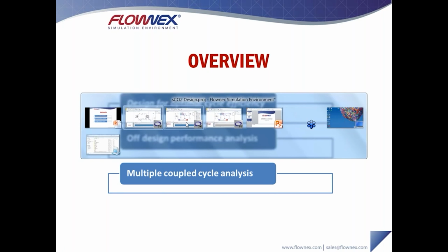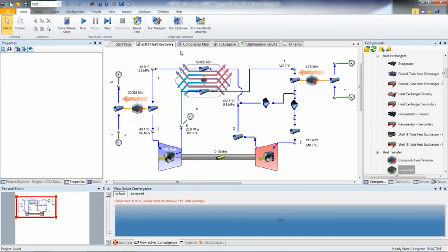Starting with the first cycle, over here, we have a heat recovery CO2 cycle. On the right-hand side over here, I have the outlet from a gas turbine, so 550 degrees Celsius. And then this heat is then used as the heat input to our heat recovery cycle in the center here. On the left-hand side, I simply have my heat rejection modeled as heat rejection into a water stream. This cycle over here consists of a compressor, a turbine sharing a common shaft, a recuperator, and then a couple of valves which I'll use to bypass the turbine. I'll discuss this a little bit later.